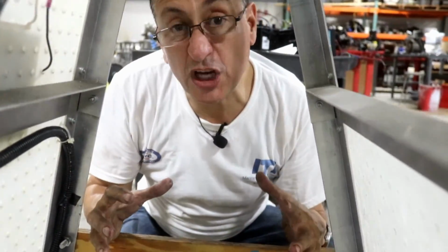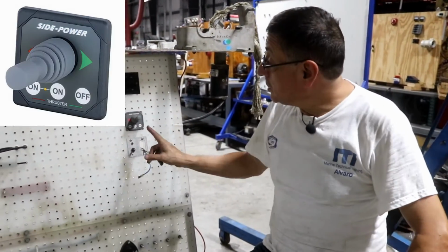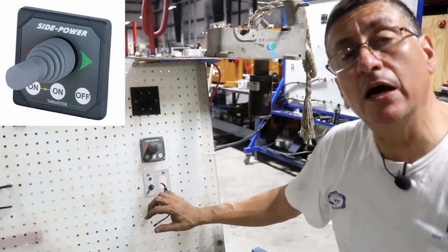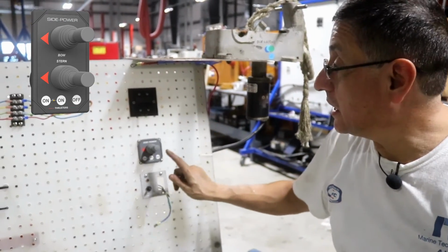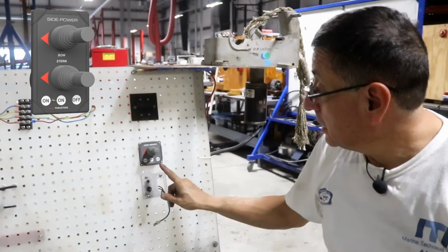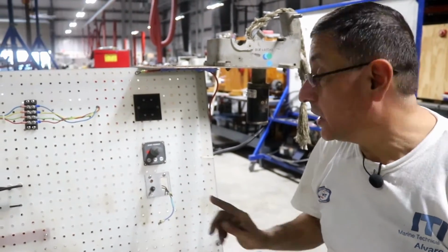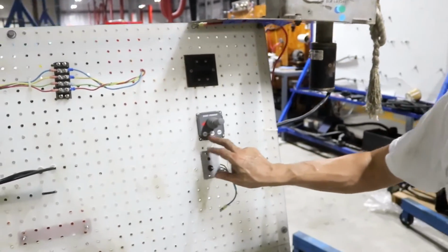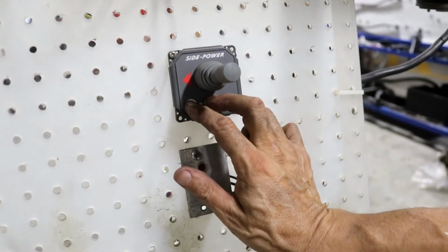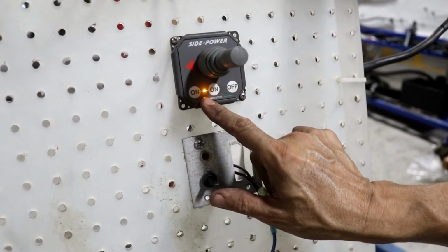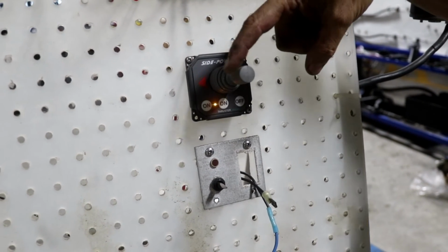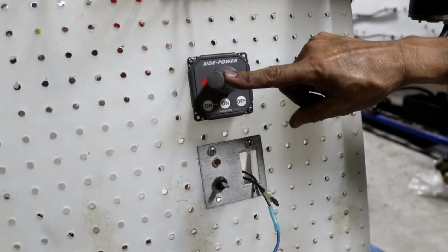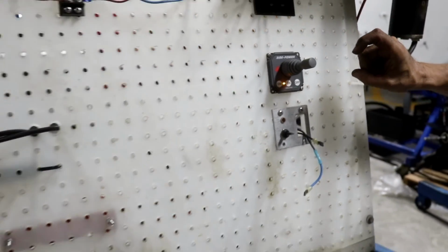Right now we are going to check the connection on the joystick and how to start the system. This is the joystick, like the joystick that you have on the screen right now. There is a double joystick, like the one on the screen, for bow thruster and stern thruster. In this particular example it is single. If you check the button, they have two ONs. If I press both ONs at the same time, right now the system is on. And I am ready to activate the bow thruster in one direction or the other direction.